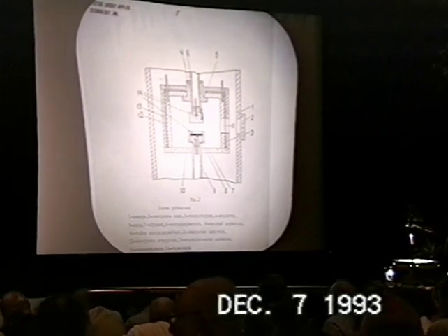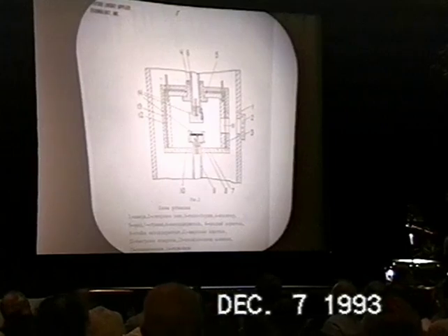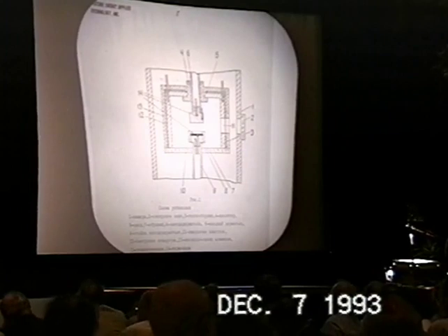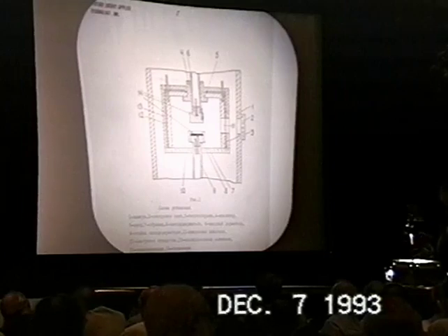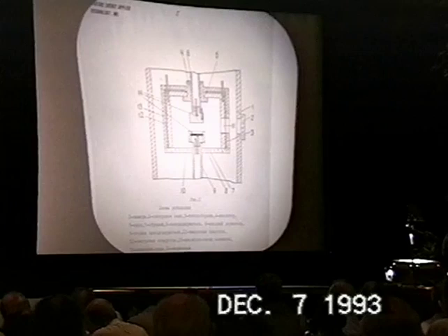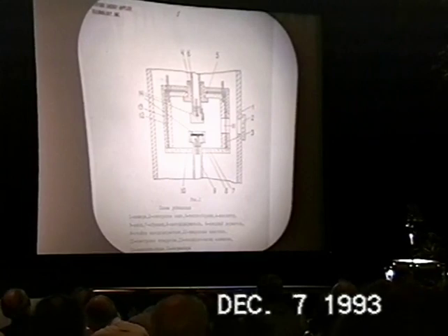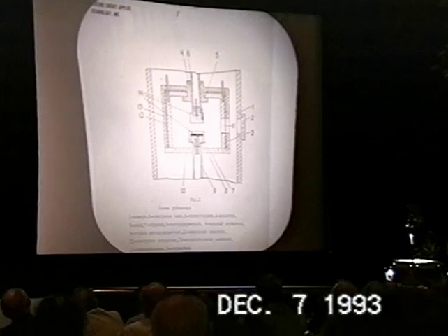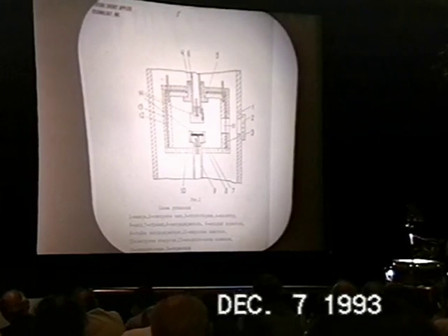So here is a cathode, here is a massive molybdenum substrate with a heat flow measurement device, so there is a space with thermocouples which measure temperature gradients. The same thing in the anode, and there was a massive copper heat collector insulated inside with aluminum and from outside, with an extensive molybdenum heat screen and aluminum heat screen outside the heat collector. From below, this calorimeter was closed with a massive quartz plate.